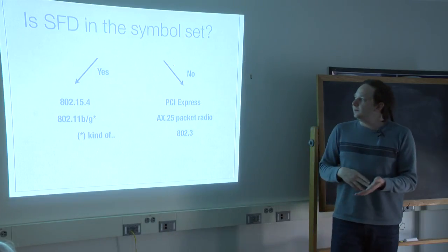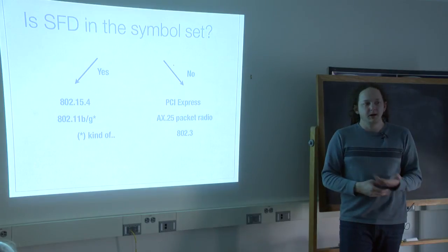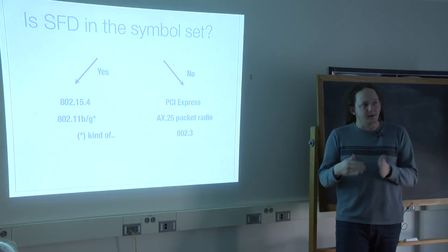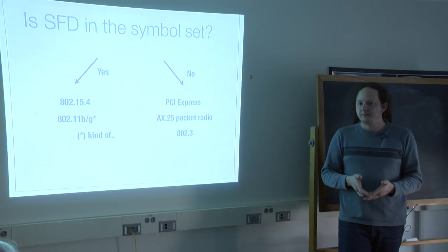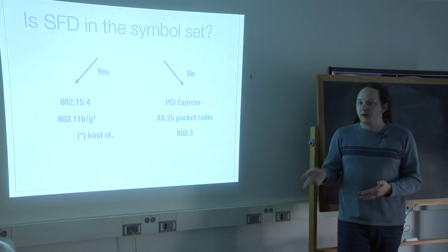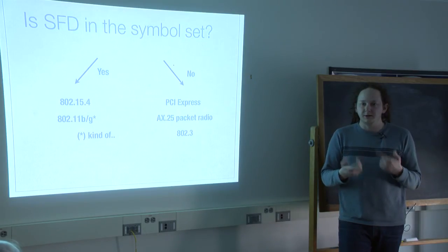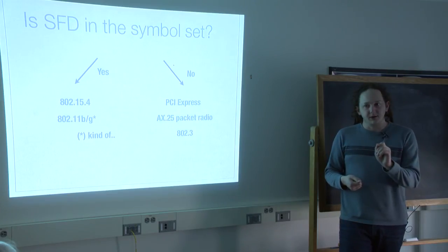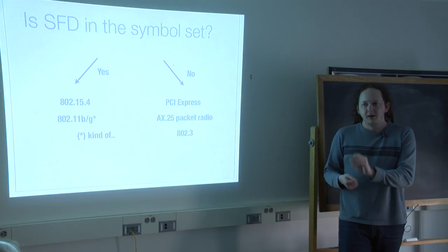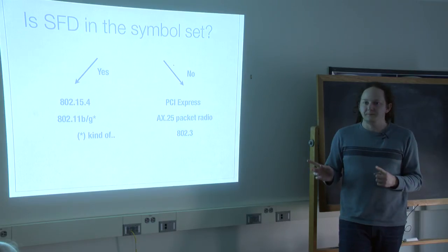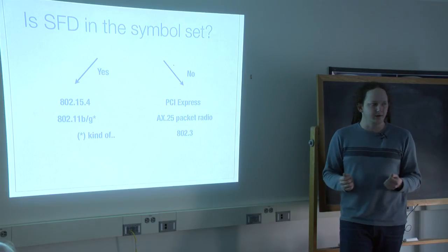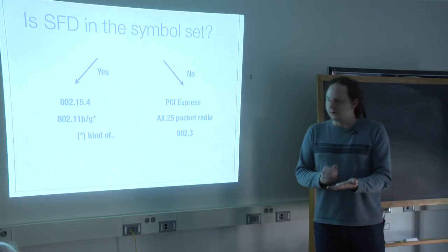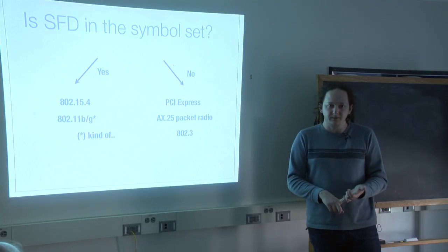But there are also extra regions in this code that would be corrected inside of a frame, but are terribly rare to reach. So these serve dual purpose, in that you can never create these on the inside of the packet, but they mark the beginning and the end. So there are special control sequence codes, one of which is a start of frame marker, one of which is an end of frame marker.